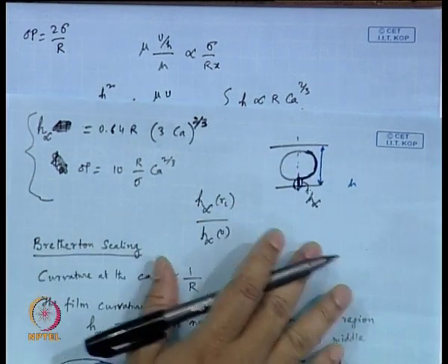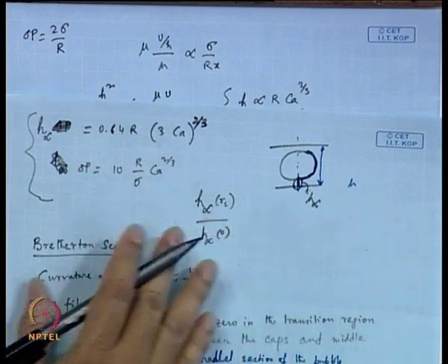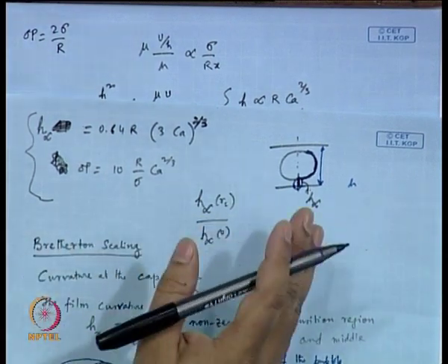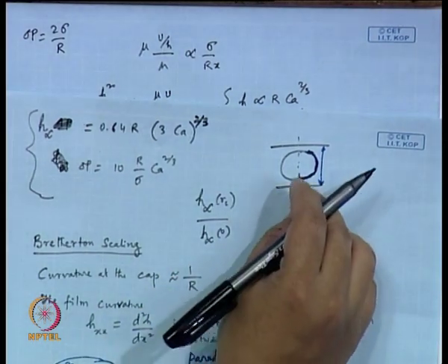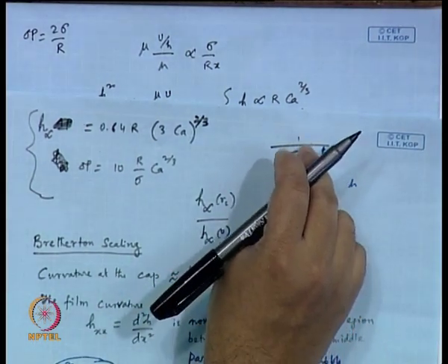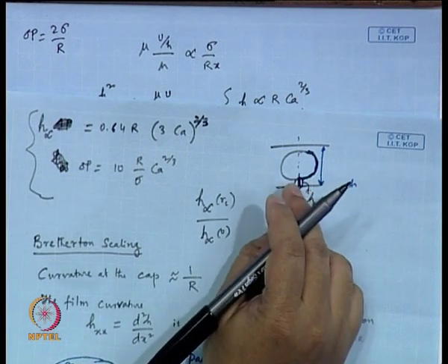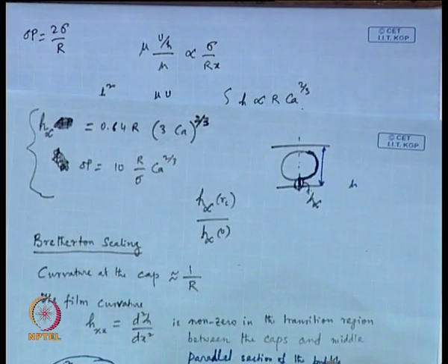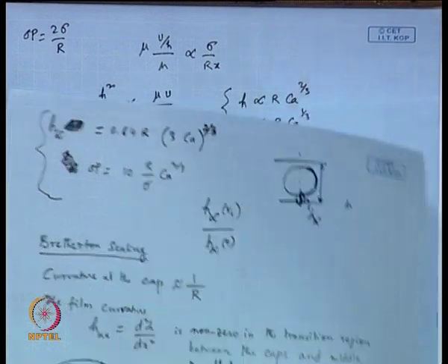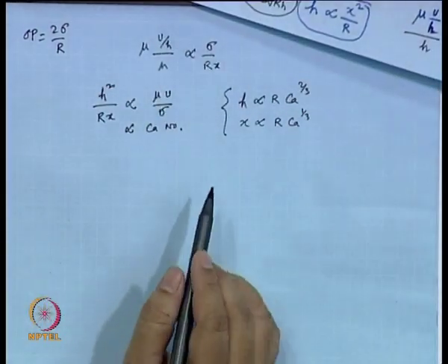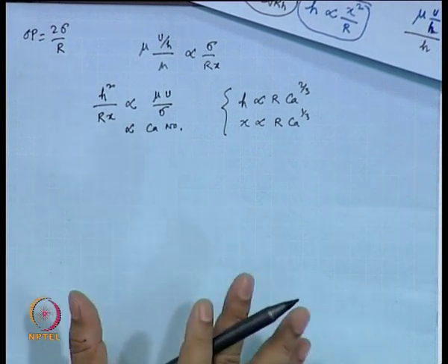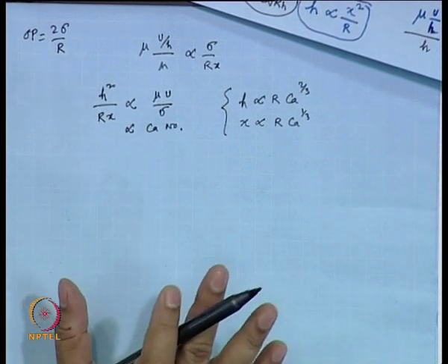You are introducing immiscible phases into the microchannel, but it would split into an annular portion for the liquid part, and the other part, the droplet or the bubble, at an axisymmetric location. But what are their dimensions? Without getting into a rigorous calculation, you can get some idea of these dimensions simply from scaling.